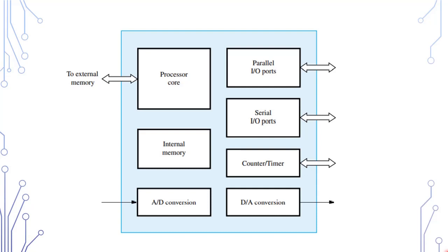The main part is a processor core, which may be the basic version of a commercially available microprocessor. Usually, we choose a microprocessor architecture that has a proven record and is popular in service. It is useful to include some memory in the chip, sufficient to satisfy the memory requirement of small applications. Some of this memory has to be RAM type to hold the data that change during computations. Some should be read-only type to hold the software because the embedded system usually does not include a magnetic disk.